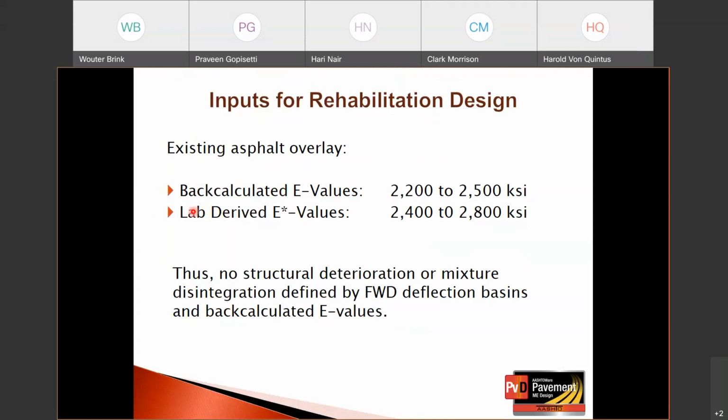If we take that default master curve and then we just look at the laboratory derived E values for the frequency of 30 hertz from the FWD, at the same temperature levels, and the temperatures, I didn't mention it previously under the FWD, but the surface temperatures were about 57 on the average, 55, 57.